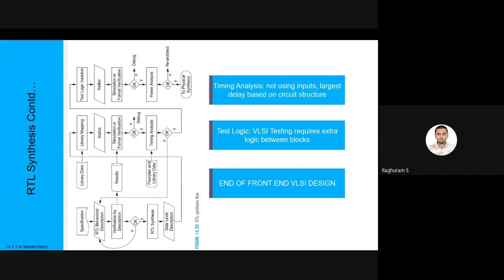Then it orders all those paths in terms of the logic. Each of these paths is going to have a few gates: AND gate, then AND gate is given to inverter, inverter is given to a buffer, buffer is given to another gate, etc. And it orders all these paths in terms of the timing. Each gate, the layout information produced, also has the timing.